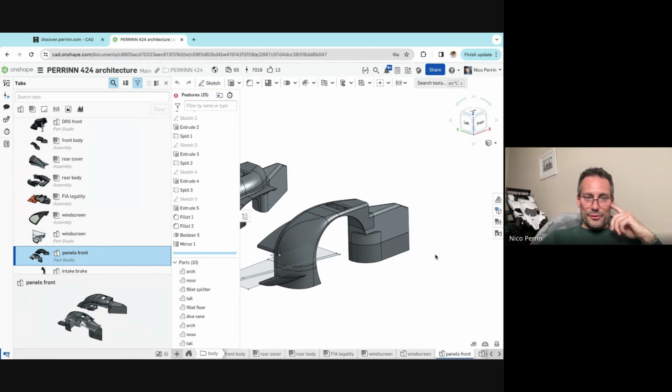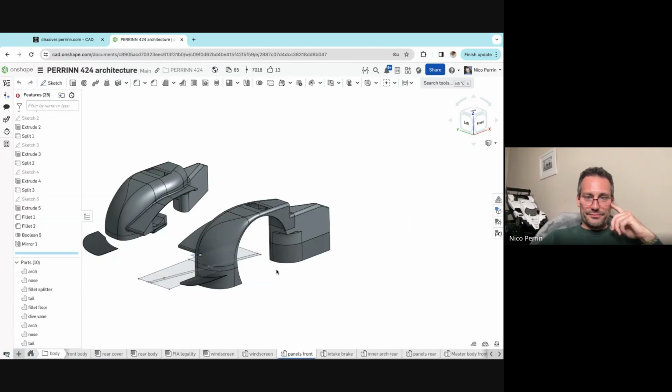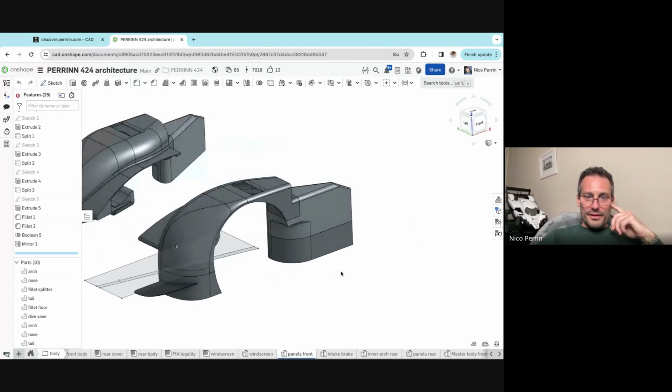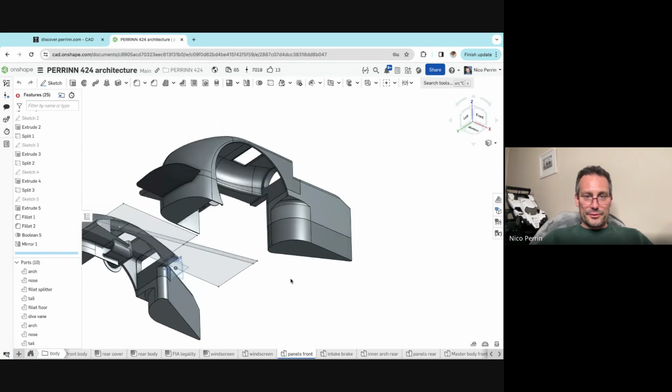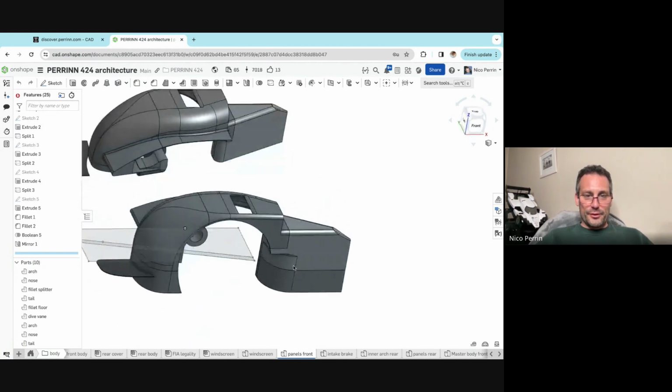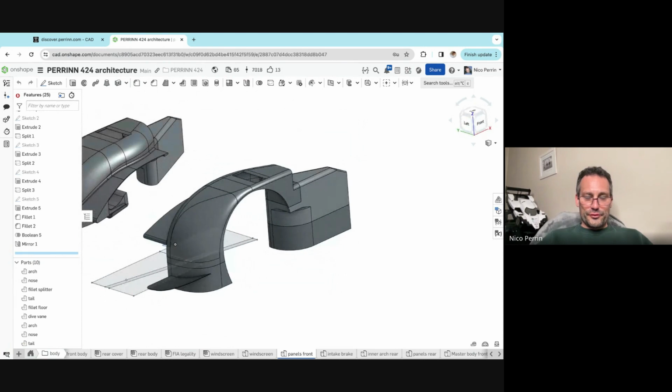So this is why when you look at components like this, I know through experience, so this is the front wheel arch, that we need to create this sort of fillets at the back of the front wheel in order to help, if you like, the flow behind the front wheel navigate on the side of the car and have better quality.